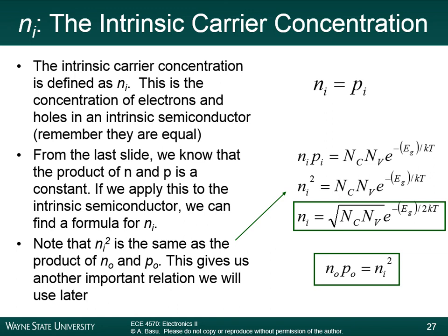This is where we talk about the intrinsic carrier concentration. We defined that earlier. Does anyone remember what intrinsic carrier concentration is? We defined it, I believe, last Thursday. Number of electrons per cubic centimeter for non-doped. Exactly. Very good. It's the number of electrons or holes per cubic centimeter in an intrinsic, non-doped semiconductor.